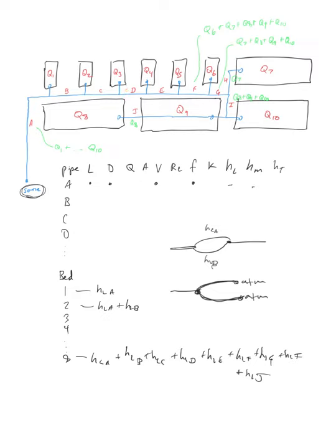And so most of the flow would go to Q1, because there has to be a lot less flow along the long path so that the velocities are low, so that the friction losses are also low. There's so much more length there accumulating in the Darcy-Weisbach equation than there is along this path, right? So you have a lot more flow going to Q1 than to Q8.